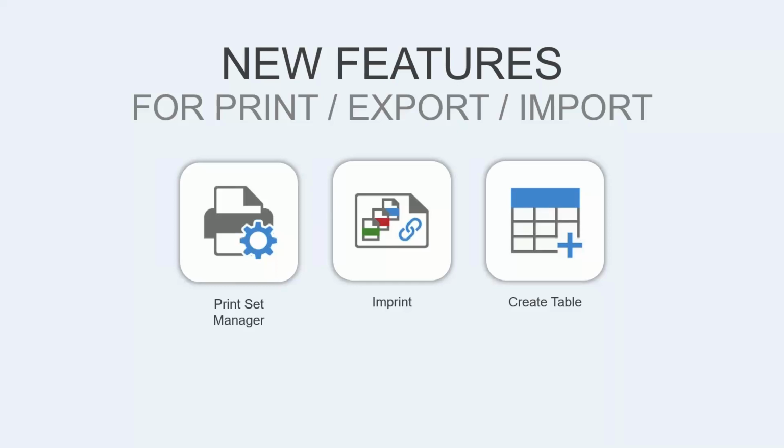Create table only works with Excel and will convert your Excel table into either a dummy schedule or a drafting view as lines, text, and filled regions. This is also a link, so you can make changes in Excel and update it back into Revit. So let's take a look at those.